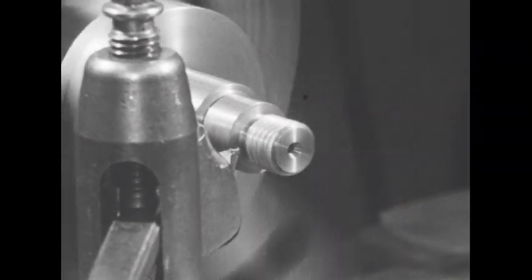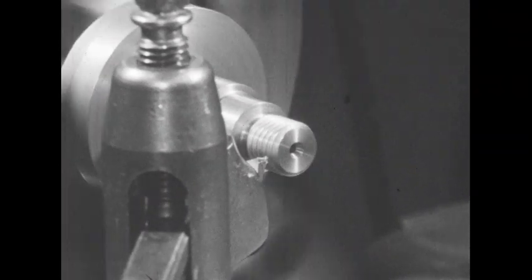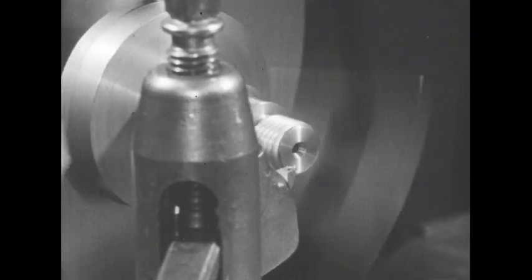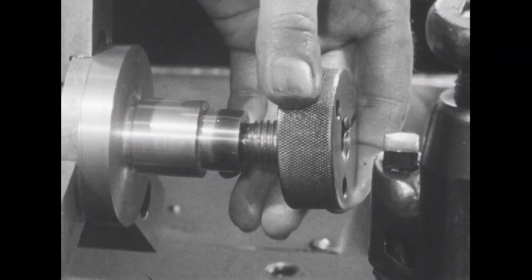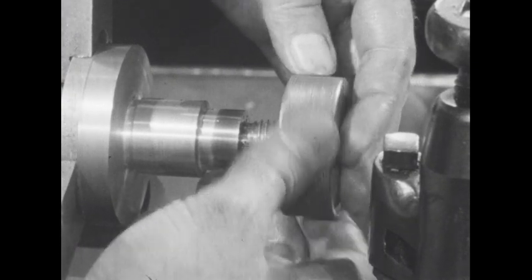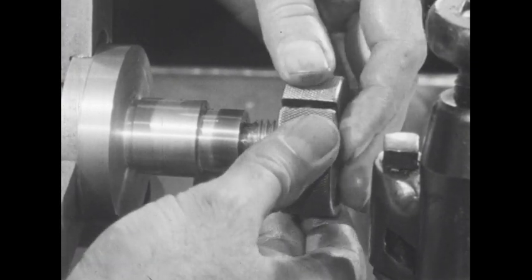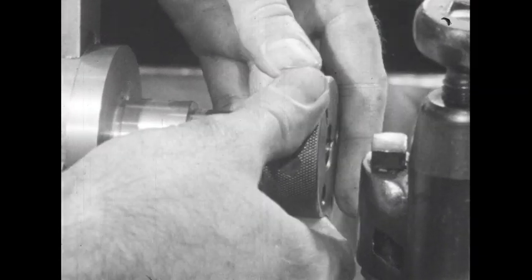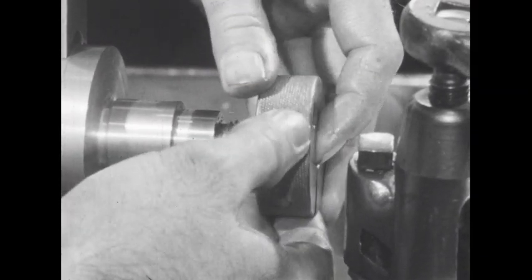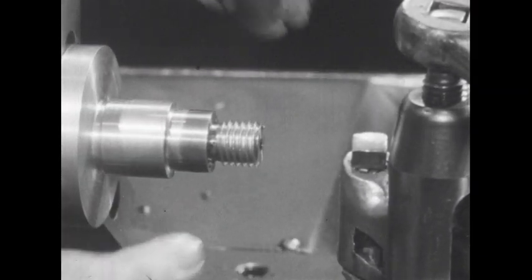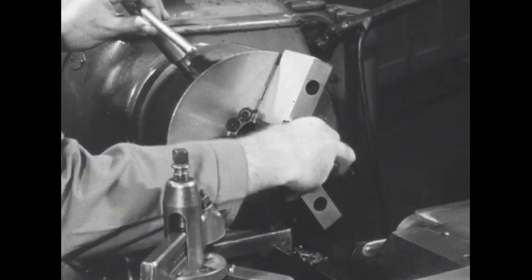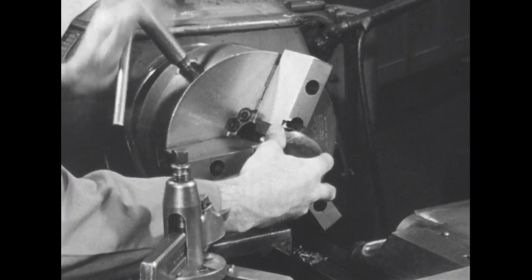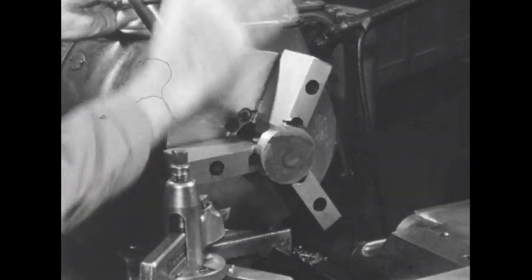The machinist must therefore proceed with extreme caution, take small cuts, and stop the lathe frequently for checking, using a specially hardened and round gauge. All the preceding operations were performed in one lathe setup, but we now have to reverse the workpiece in order to bore the other end.